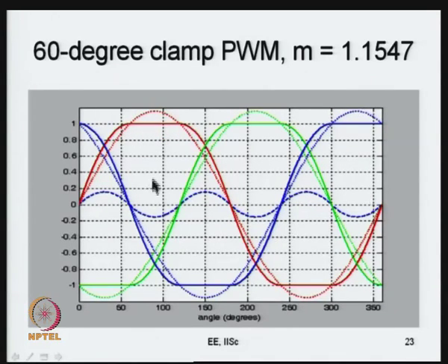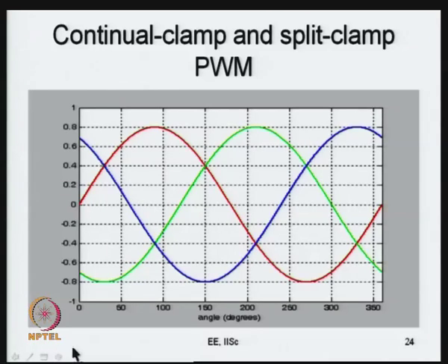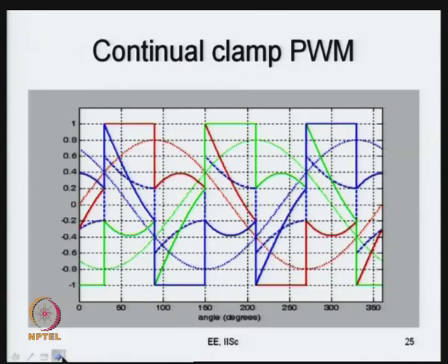If the R phase current is going through a 0 crossing here, not much saving is obtained, and if the R phase, for example, has its peak here, when R phase is switching, not much is obtained here. So, you have this thing of phase shifting which you can normally do. Now, for example, if the R phase in this case is leading, the current is a little leading, then you can go in for a clamping as shown here now.